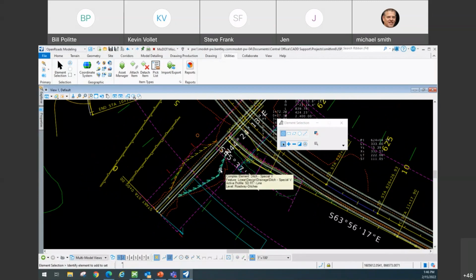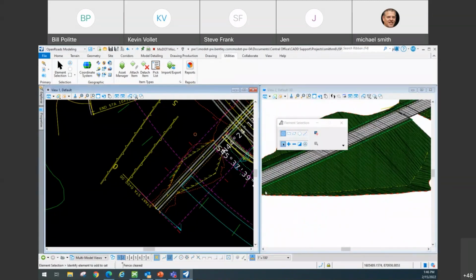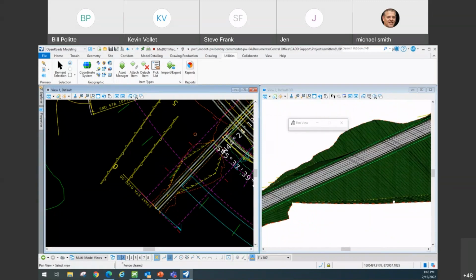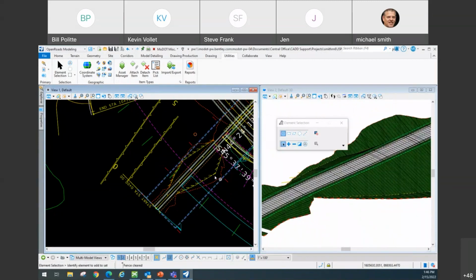This file is the plan file. So you can kind of see I've got a couple of ditches drawn in here. If I hit F6 on this, they're basically just a ditch line that I've carried from one ditch to the other. You don't ever design your project this way, but that's beside the point. Wanted to just show that this is a point controlled element. So our end conditions go out and seek these lines, but I want those to show up in my profile for my mainline roadway on the corridor. And then I also want to see what the existing ground looks like 30-foot left and right of that.